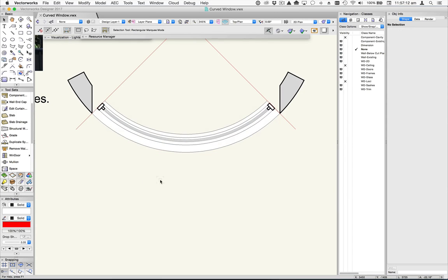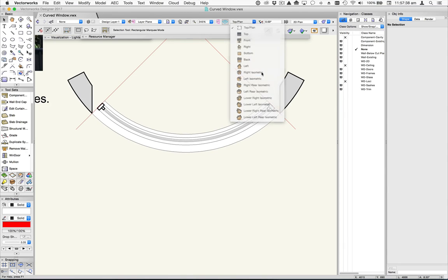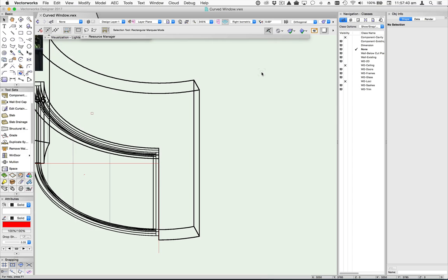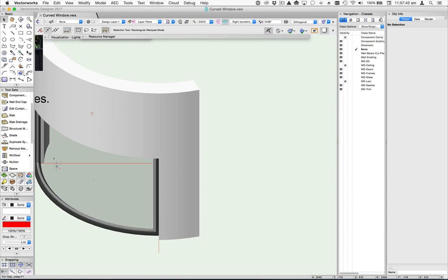and you can see that when you put a round symbol into a round wall, the symbol wants to make this kind of cut here, straight up from that outside point on the wall. So we have to create these little filler pieces within the symbol to counter this. In 3D, the wall hole object is doing its job fine, which you can see here.